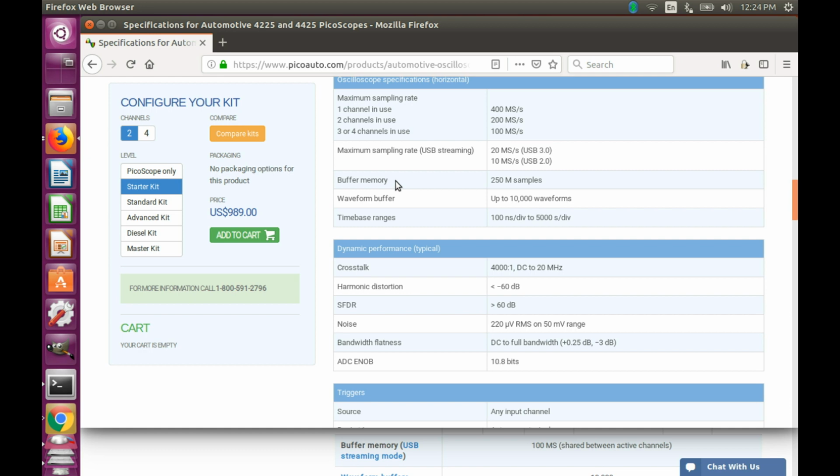One thing to note, it can sometimes be confusing whether your Picoscope is in the block mode or the USB streaming mode. And actually there are preferences where you can set when you want one mode or the other mode. So please look up the help in Picoscope on that. Sometimes it's helpful to have a properties dialog open in the Picoscope so that you can see what the sampling rate is.